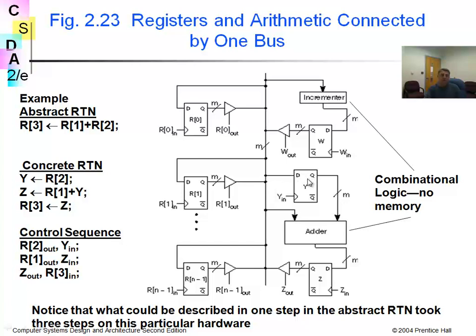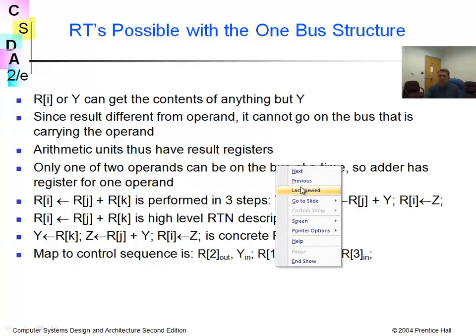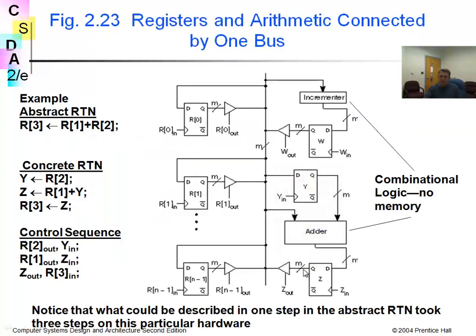There are n bits, so if it is 32-bit, you have 32 of these, and then you bring R2, for example, from here, and right to here, then you add them up and you take the results and store them in R3. By having everything ready here, you enable this one and it automatically goes to the right register. How? By only taking the clock of that register, that flip-flop.